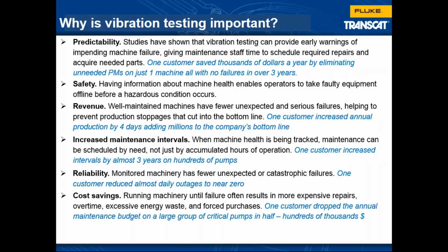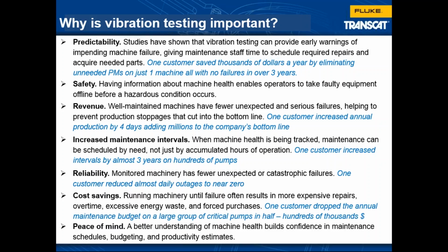So, cost savings from energy waste. A lot of people think about production and maintenance cost, but what about energy savings? Just having a machine a little bit out of balance or misalignment can cost thousands of dollars a year in energy. Peace of mind. What machine keeps you up late at night? Let's see if we can find a way to make that machine more reliable and easier to maintain.